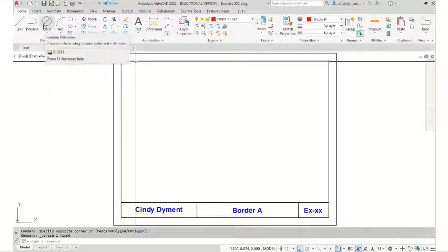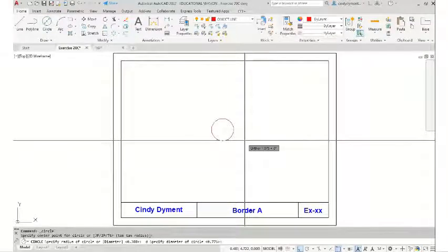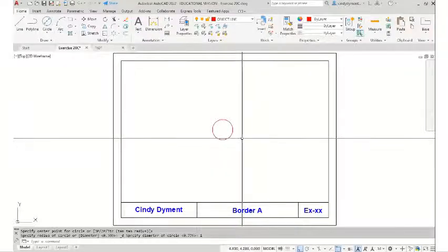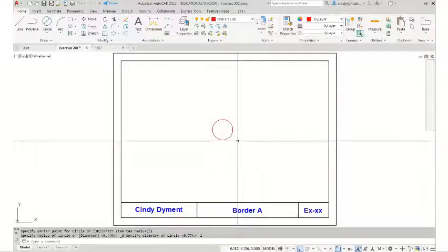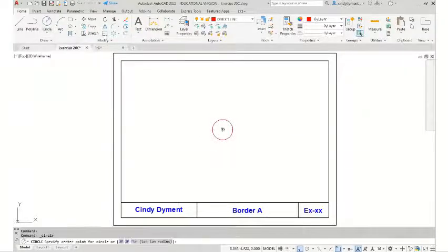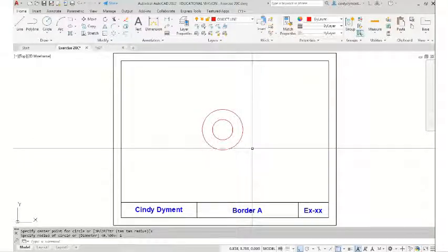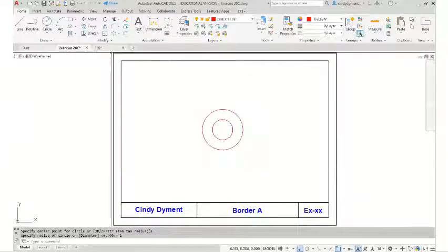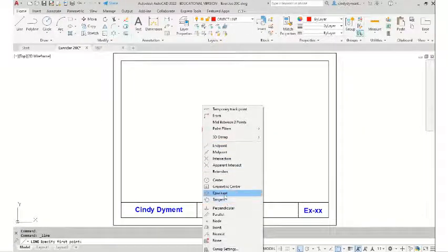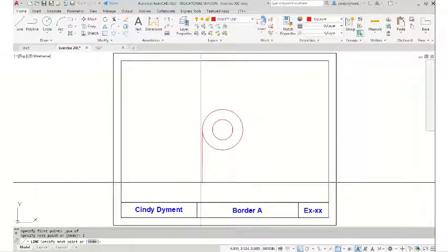The circle has a diameter of 1. And then we have another big arc on the top with a radius of 1, and it has the same center as that circle. So come in there, type in 1. Now I am going to go from the quadrant point and come down 2.